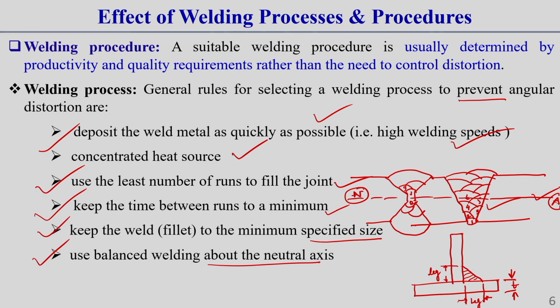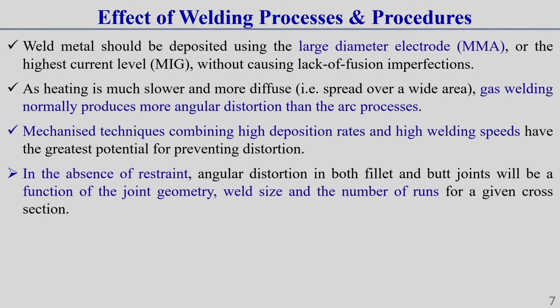So, what I am saying is, instead of doing the welding on one side, if we do the welding on both sides, then that gives less distortion. This you should also keep in mind. Now, here I have already written some very important points on the effect of welding processes and procedure, like weld